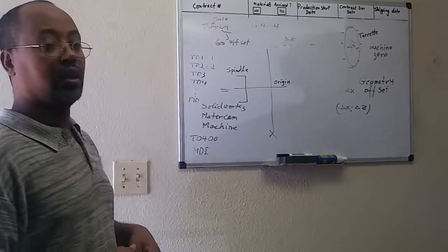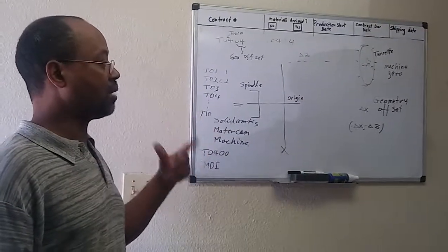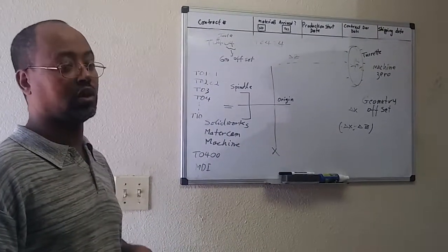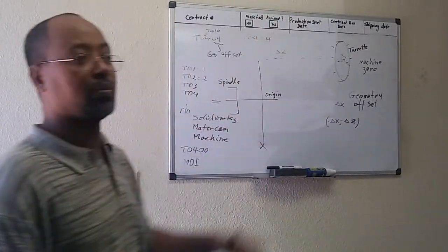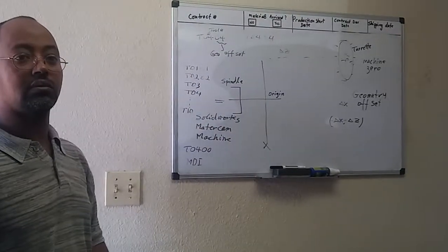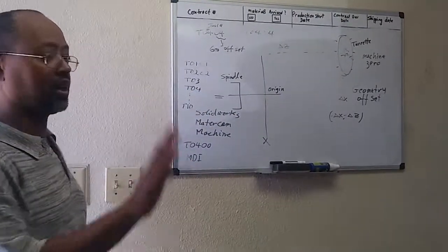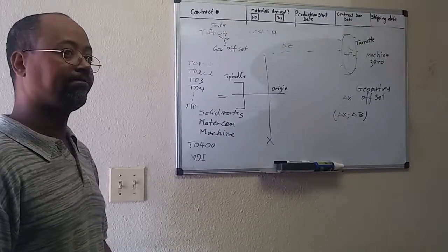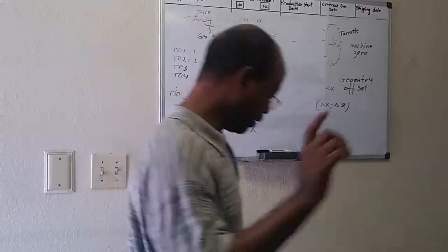And without a geometry offset, do we have the machine, Mastercam, and SolidWorks communicating from the same point? No, we don't, because the machine has its own 0 position. You have to use those numbers to bring it to the origin. Now all three are shaking hands. They are talking the same language, okay? Clear? All right. So we're going to go to the machines.